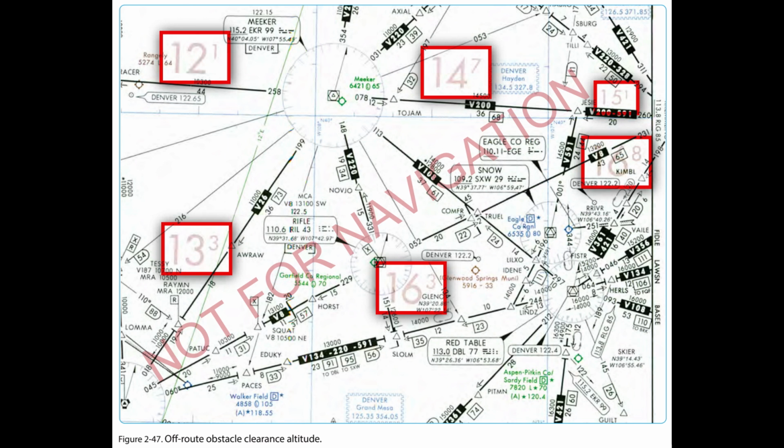For all random RNAV flights, there needs to be at least one waypoint in each ARTCC area through which you intend to fly. One of the biggest problems in creating an RNAV direct route is determining if the route goes through special use airspace. For most direct routes, the chances of going through prohibited, restricted, or special use airspace are good. In the United States, all direct routes should be planned to avoid prohibited or restricted airspace by at least 3 nm. If a bend in a direct route is required to avoid special use airspace, the turning point needs to be part of the flight plan.